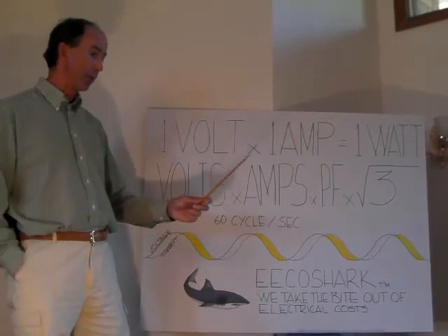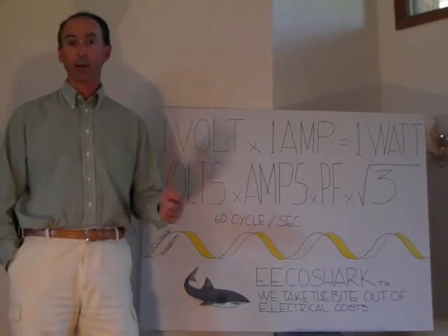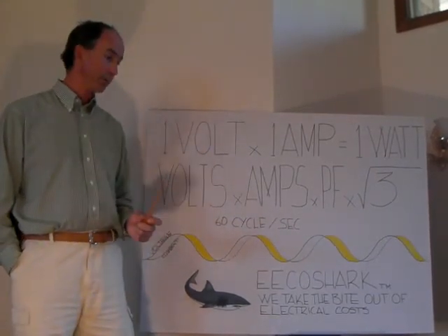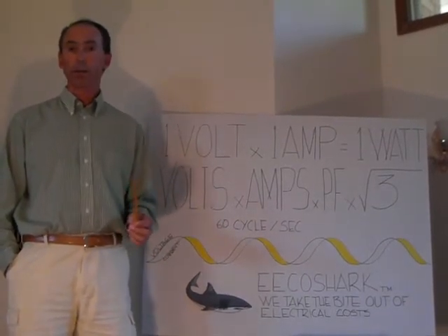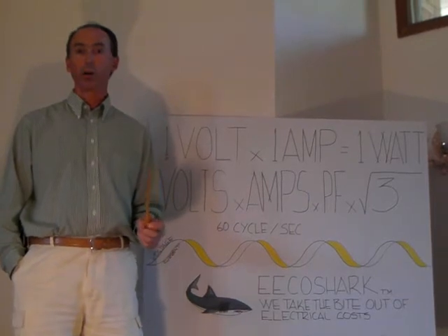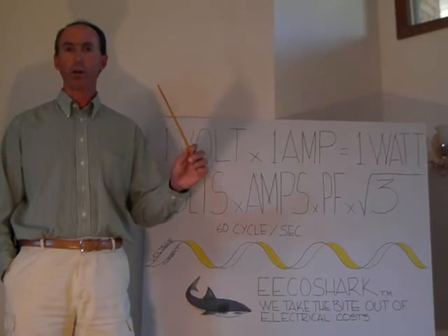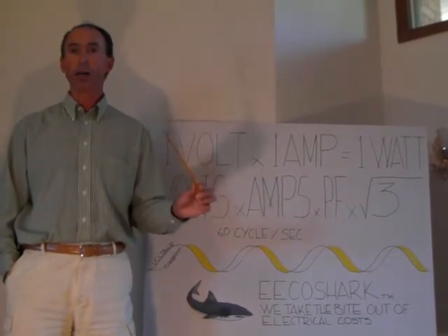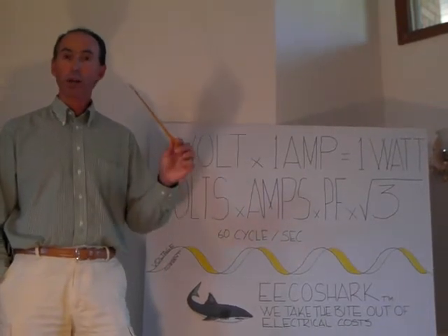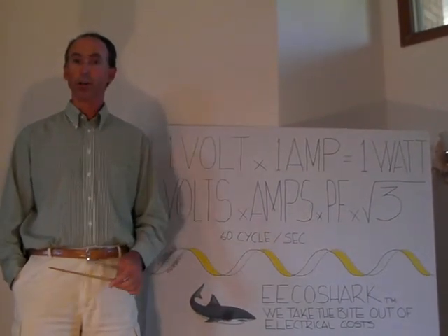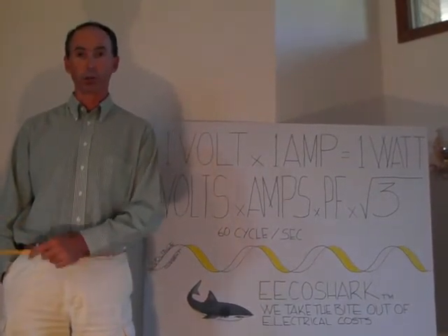The next line item on your power bill may be some component of demand. Say, maybe it's peak demand. Well, peak demand is a function of a 15-minute billing cycle that runs all year long, and the highest point in that 15-minute cycle anywhere in the year is your peak demand for the next 12 months. So, if you can lower peak demand for this year, then you will reap the benefits of that for the next 12 months continuously.